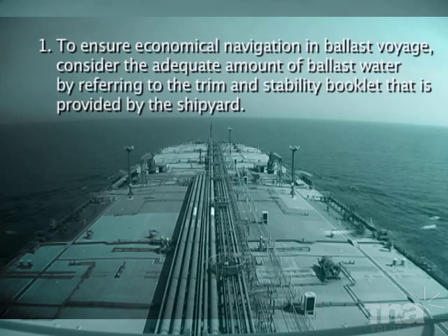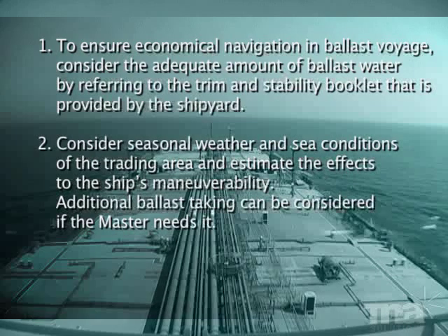One, to ensure economical navigation in ballast voyage, consider the adequate amount of ballast water by referring to the trim and stability booklet that is provided by the shipyard. Two, consider seasonal weather and sea conditions of the trading area and estimate the effects to the ship's maneuverability. Additional ballast taking can be considered if the master needs it.